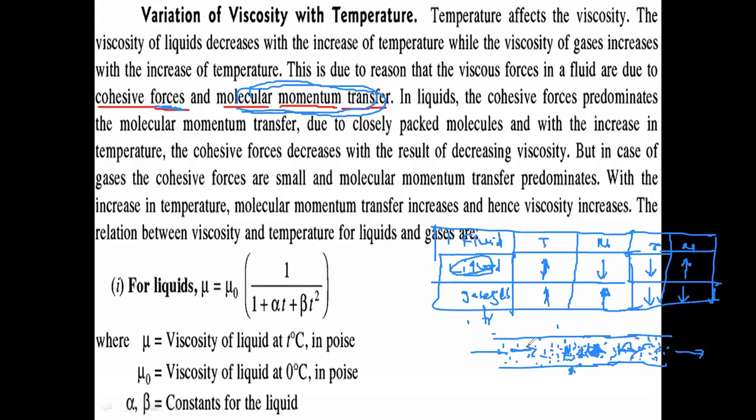What is viscosity? It is the resistance offered by molecules to the movement of other molecules. If they are colliding with each other, then how will they move in this direction? So in case of gases, with increase in temperature, viscosity will increase. And if you reduce the temperature, the energy absorbed by the molecules will decrease, means their momentum will decrease, and eventually the transfer of momentum from one particle to another will decrease, and thereby viscosity will decrease.